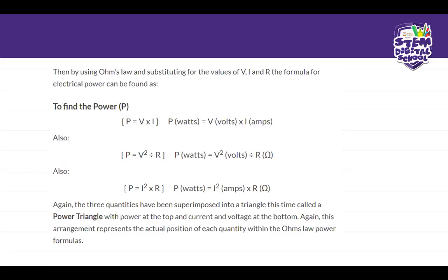For example, if you were given current and resistance, you would have to substitute Ohm's law into your voltage, and that will be voltage is equal to current times resistance. That's the formula for voltage: voltage is equal to current times resistance. So in this case, it will give you I squared times R. I hope that you guys now understand how you got your power formula and where all these squares and resistances come from after being told that power is equal to voltage times current.